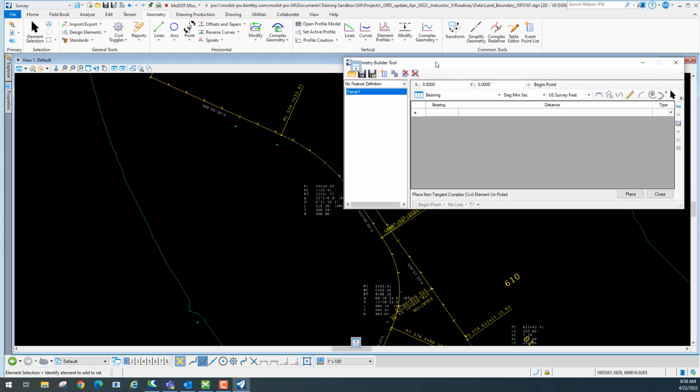The one thing we want to look at is where we want to begin this. Right now it wants to begin it at 0, 0. I want to begin it on this point 800. So there's this begin point option here. Just to the left of that's the little plus. Select begin point. So we're going to left click on that. And we're going to come out here, and you should get right over the top of 800, get the golden X, and just left click it. And that sets up your start location X and Y.